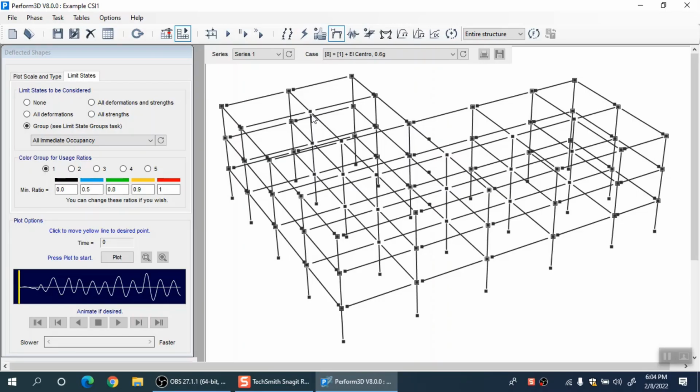All those degrees of freedom which have the lumped mass have the tendency to produce dynamic effects. But the degrees of freedom associated with dynamic analysis are generally fewer than those which are required to capture the K matrix of the structure. This requires some explanation. Let me try one more time. For example, we generally lump the building mass at each story level. So the program can make the M matrix based on those lumped masses. Now the lumped mass at each story level is just one mass containing, let's say, 3 degrees of freedom, right.